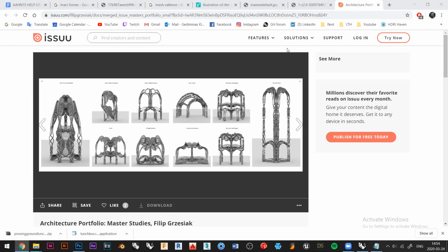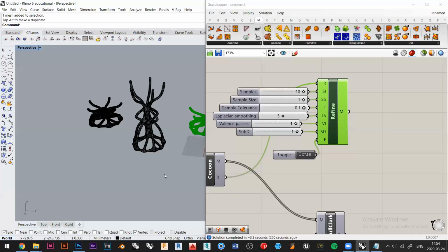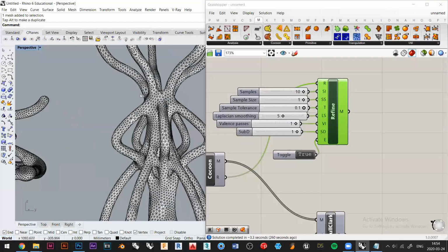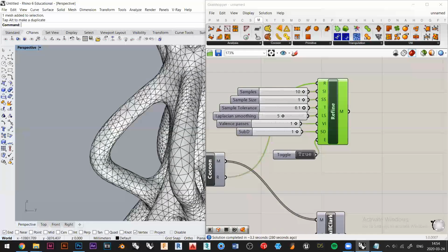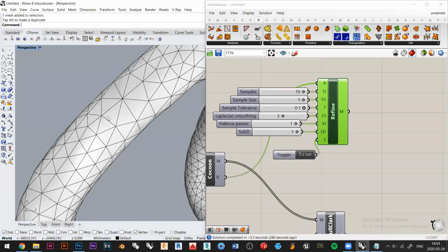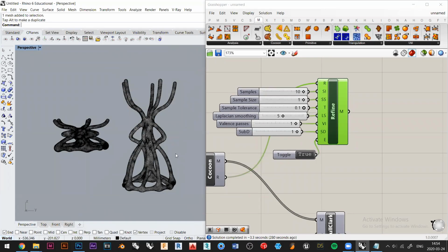No. Yes, kinda. If you try to make this mesh into a closed solid polysurface, it will not work. It will work, but your computer will not handle it. It will crash your computer, unless you have a really strong computer. Because it's going to take every polygon and make a surface out of every polygon. So imagine how heavy that polysurface is going to be.